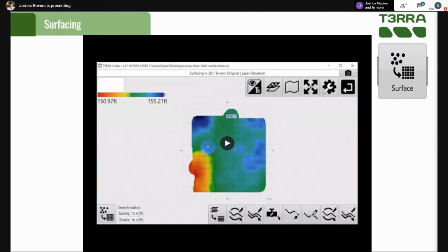It looks a certain distance away in every direction to find an actual surveyed point. This distance is called the search radius. Once it finds enough points, it will estimate the blank location based on the fixed data captured.